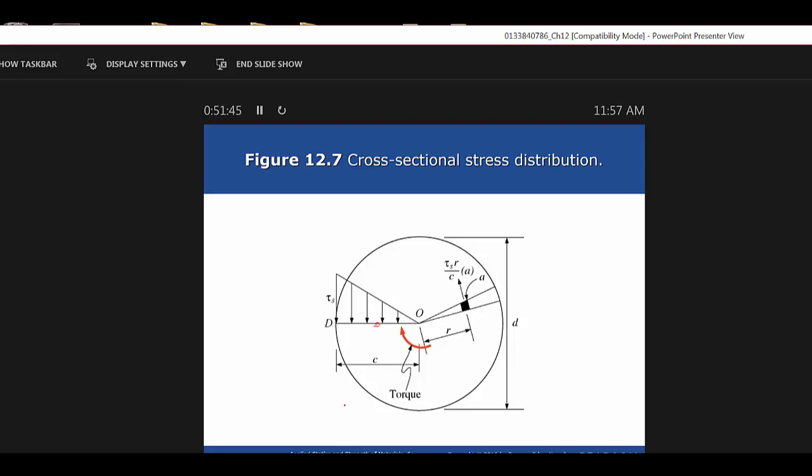Okay? Now the torque equation, if you look on page 251, if you're wanting to find torque, the torque is equal to the shear stress times J. Well, what's J? That's the polar moment of inertia. And note, you will be able to find that on the back cover of your book. Divided by c, which is the radial distance from the centroidal longitudinal axis to the outer surface, or to wherever you're trying to find that value.